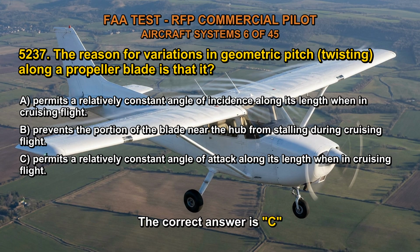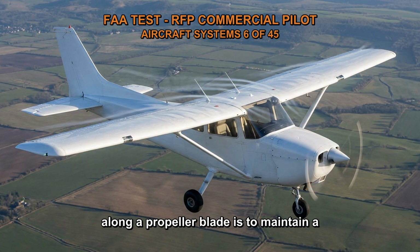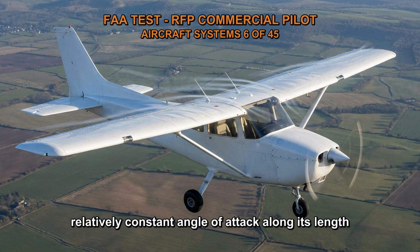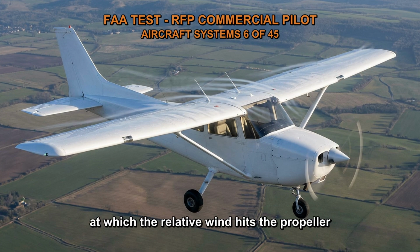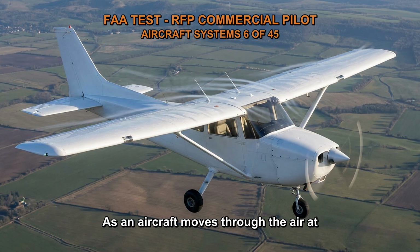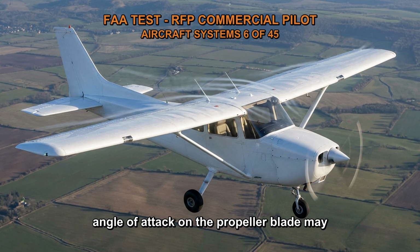The correct answer is C. The reason for variations in geometric pitch, twisting, along a propeller blade is to maintain a relatively constant angle of attack along its length when in cruising flight. The angle of attack refers to the angle at which the relative wind hits the propeller blade. As an aircraft moves through the air at different speeds, the relative wind changes, and the angle of attack on the propeller blade may vary.